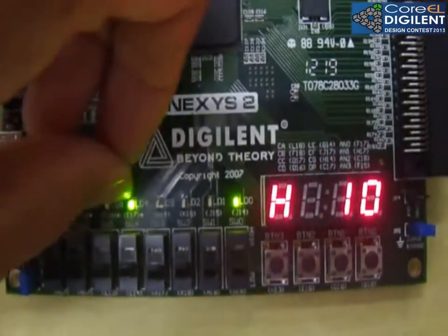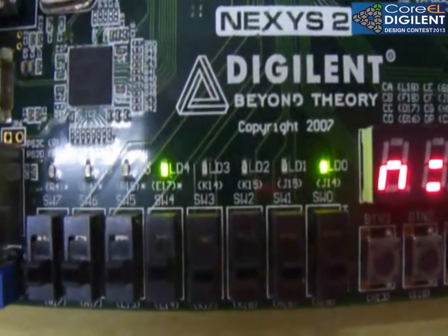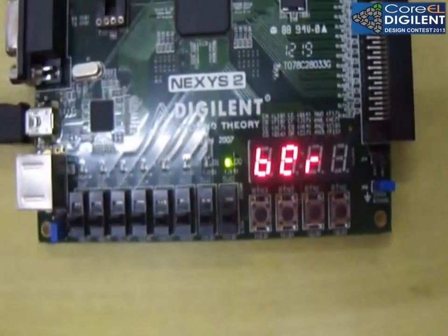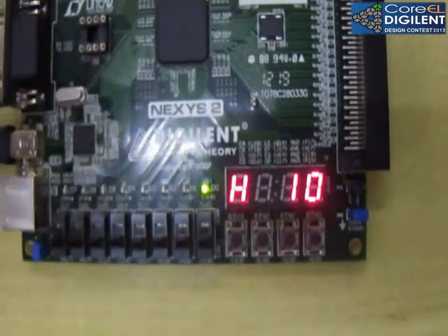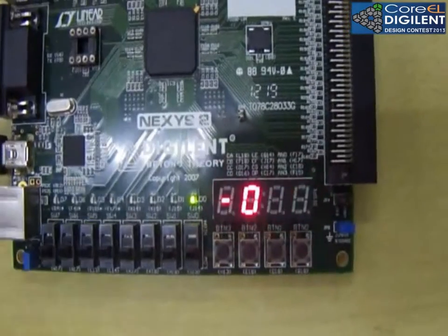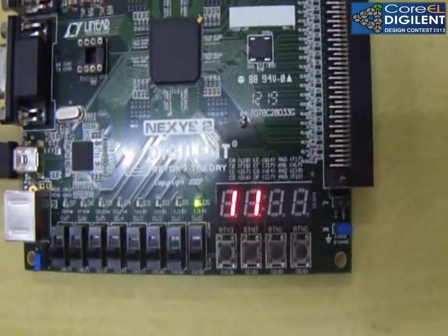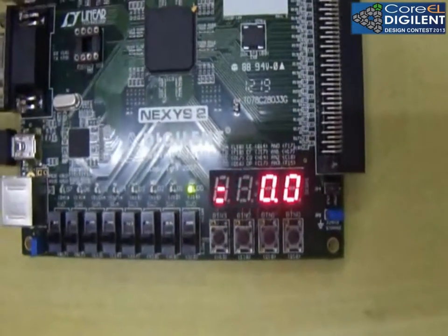These five LEDs indicate the errors introduced at different powers of 10. The first, when this LED is high, indicates that the errors are counted in 10,000 bits. When the second one is high, it indicates that it is counted in 1 lakh bits. The third one indicates that it is counted in 10 lakh, and the last one indicates that it is counted in 1 crore.